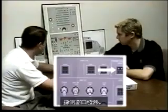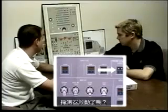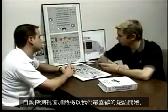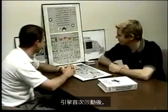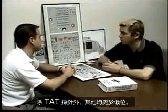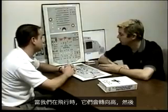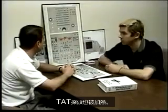Probe window heat. With the switch in auto, when is the probe and window heat activated? The probe window heat in automatic will start with our favorite phrase, after first engine start. After first engine start, all the probes and window heats are heated in low, with the exception of the TAT probe. When would they go to a high or flight mode? When we're in flight, they shift to high, and then the TAT probe is also heated.